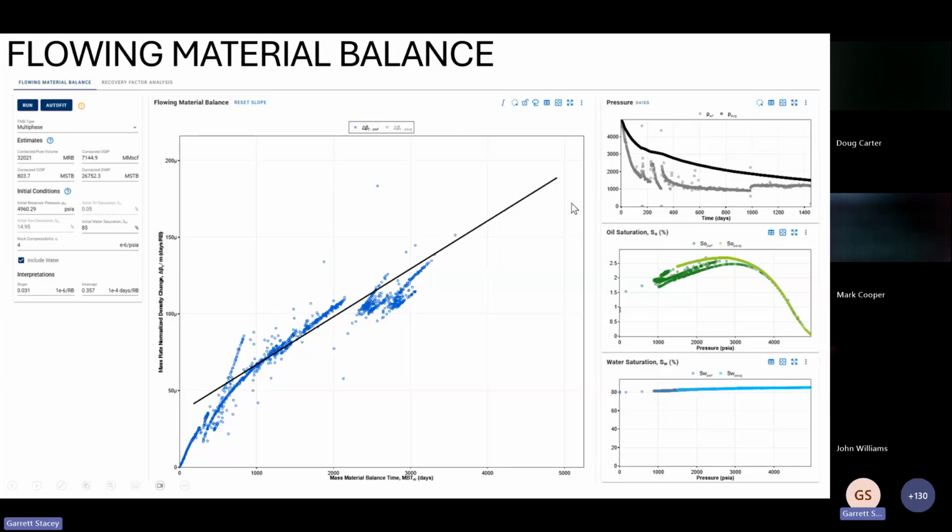But again, this is why after I make a gas lift change, I have to reiterate that gas lift change, and then also I don't take off the whole chunk at a time, and I'll get there in a minute. But this curve here, it's nice to be able to say we have to be above that producing bottom hole flowing pressure with our reservoir pressure.